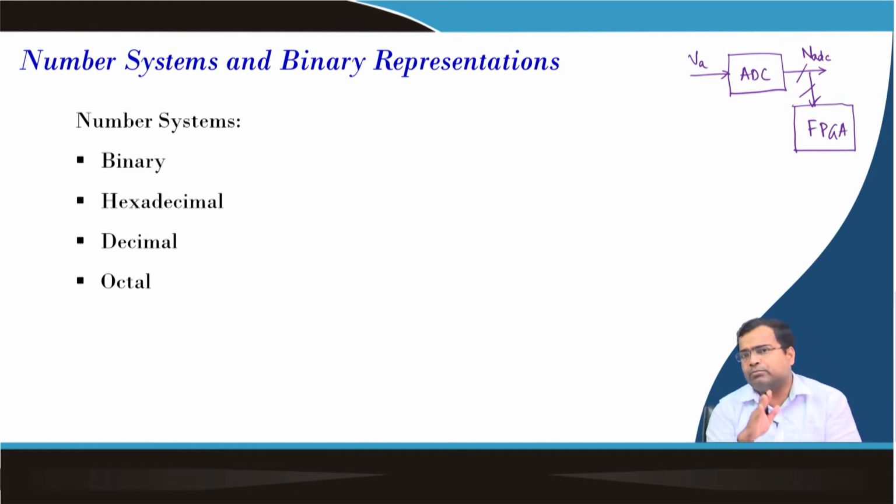Your data output from the ADC is parallel, because we want a fast ADC, typically serial ADCs are slow, but you do not have sufficient pins. So, you can use some kind of interfacing digital circuit which can convert parallel to serial, and that will be a high speed circuit, because it does not need any conversion, it is just a codification. That means you are converting parallel data into serial, and it is a coding encoder and decoder that have to be linked, and in that way you can also manage, and this encoder and decoder circuit can operate at a very high frequency.